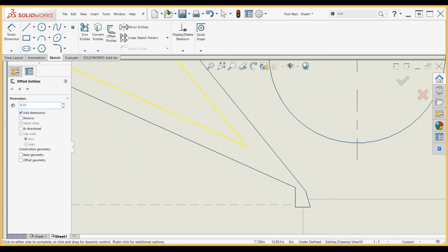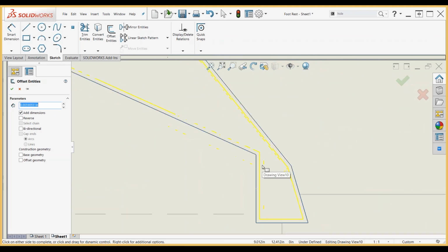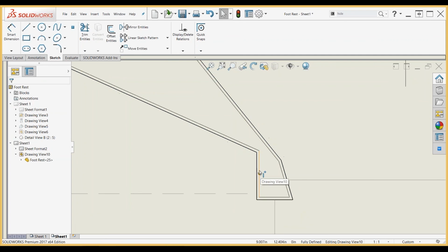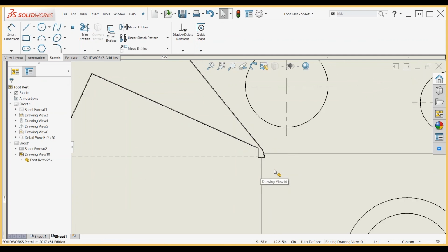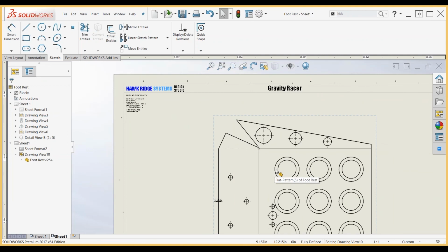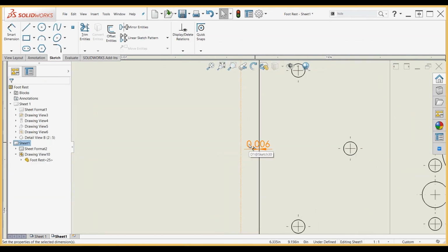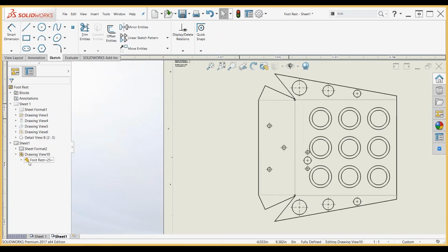So I have this other drawing here of an axle, and I'm sure you guys know how to deal with this to make it fit on your page, and that's using your break view. So you can break this view here, put your two breaks in, but trying to get them to line up perfectly and be evenly spaced on either side is sometimes a challenge.